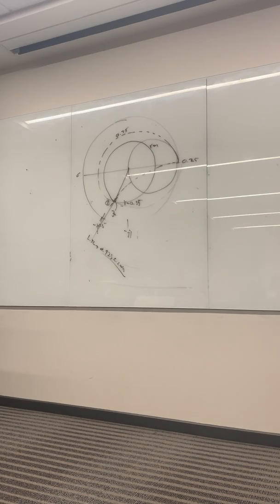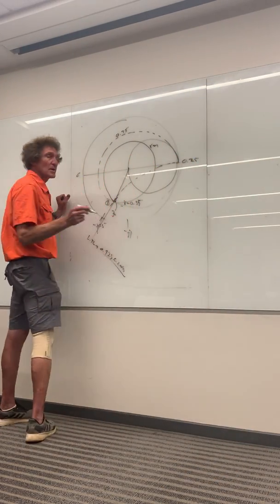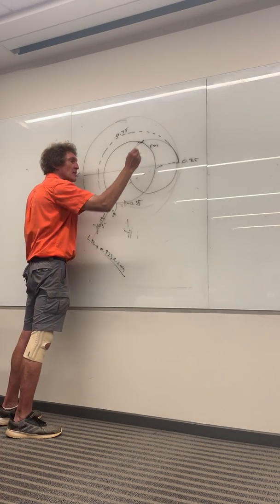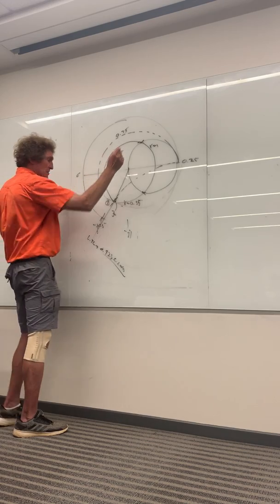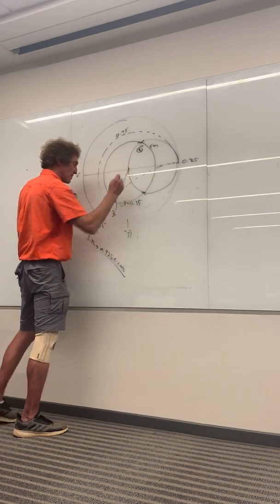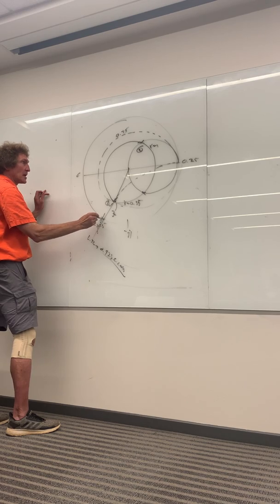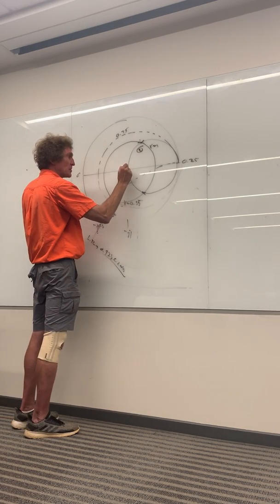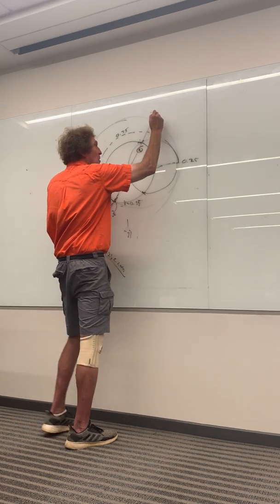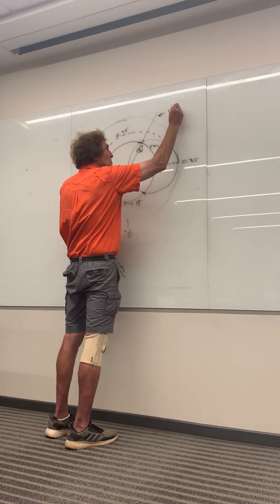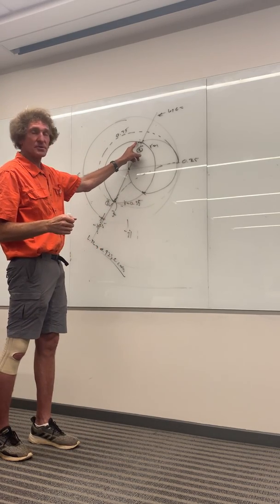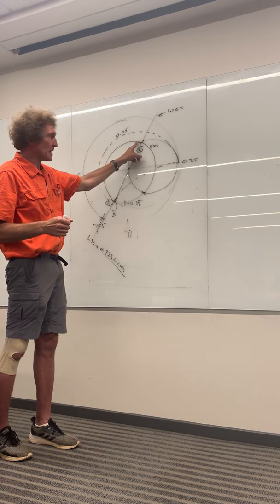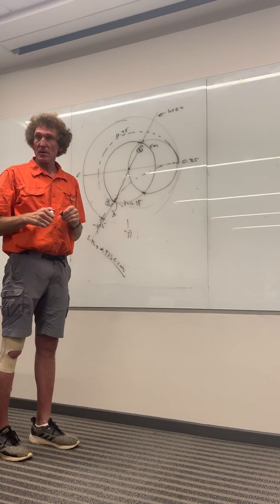All right, now, hear me. We need to go to one of two points, either this point right here, or this point. Why? Because at that point, I have 1 plus or minus j something, correct? So we're going to go to this point first. I call that point 1, and I'm going to call this point 2. So now I have to move from here, and how far do I have to move? Well, draw a straight line through this point from the origin. You're going to see a mile marker here, the wavelengths toward generator. What's that value? You've got to go right where the circle of constant reflection coefficient intersects the 1 circle. What do you get?